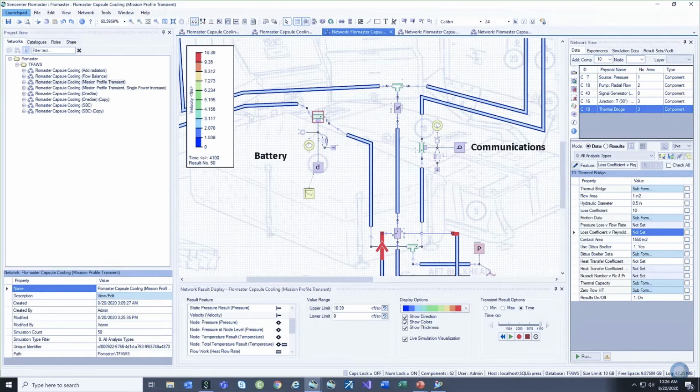Now what I'd like to do is focus a little bit on the detail here, right? In our analysis, we used just a forced convection coefficient, which assumes a cylindrical pipe. That might be fine for a simple heat exchanger or a very simplistic cold plate where you just have maybe a serpentine tube moving through a plate. But in all likelihood, you're going to have some heat transfer enhanced surfaces, things like pins or fins, to increase the turbulence, increase the heat transfer in that cold plate. And we're not capturing that here.